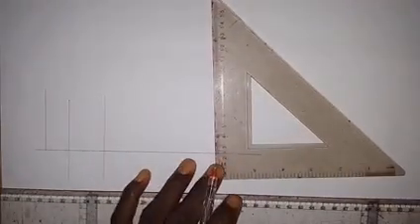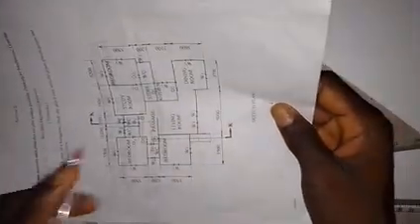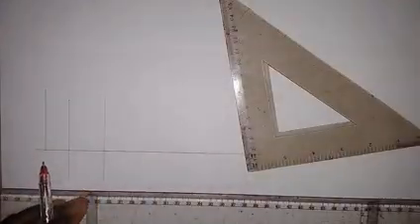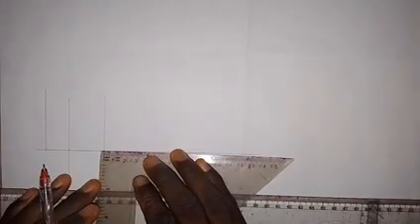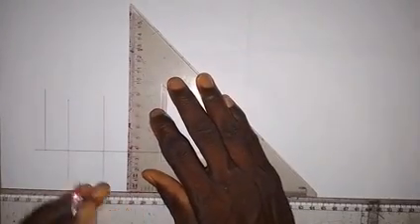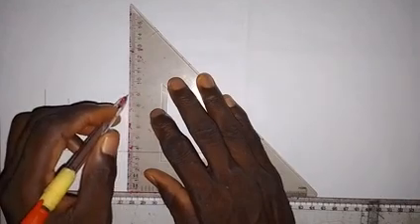The next wall that we are going to see here, whose edge we are going to see, is this wall. The distance from here to here is 1000, and 1000 by 50 will give us 20. So I have to take a measurement of 20 millimeters from this point. As I said, we are going to see the edge of that wall. So I will just draw a vertical line at this point here like this.